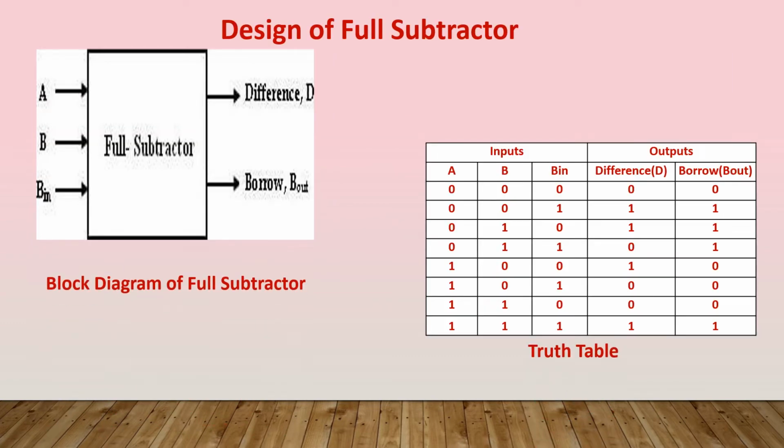Now we are going to discuss the design of full subtractor. This full subtractor consists of three inputs, that is A and B, the inputs that have to be subtracted, and the third input is nothing but borrow in. And as usual, there are two outputs, one is difference, the other one is borrow out. Now as the input and output variables are identified, and we have given the notation for both, we can construct the truth table.